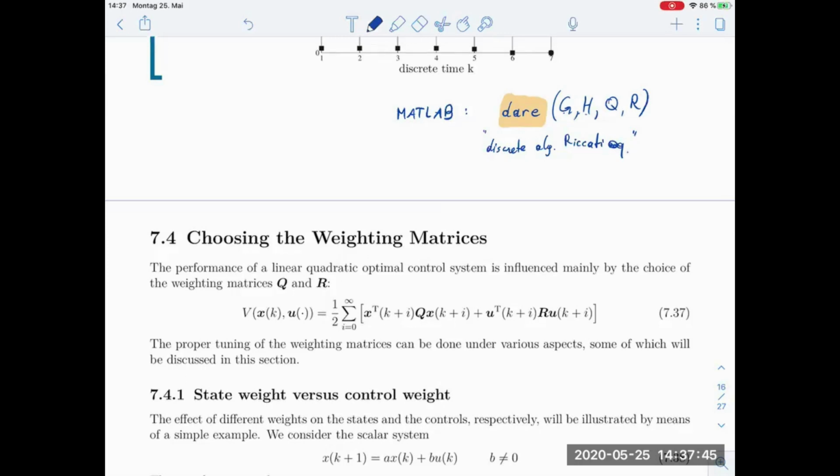And this Riccati equation is entirely different in structure. It's not entirely, it has similar structure in some sense, but it's not equivalent because there we really are in the differential equation domain, and the Pontryagin principle just looks different. The stability regions look different, and how we assess stabilization or the integration of costs. So essentially the continuous time algebraic Riccati equation has similar problems to be solved, but in detail the terms look different. So don't mistake one for the other, you will not get the right results.